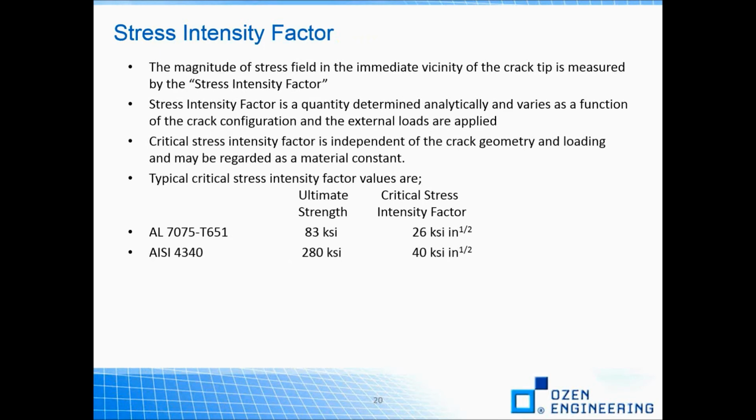So when the load and crack size are kept below the threshold point of unstable crack extension, which is region number 2 if you remember from the earlier slides, the magnitude of stress felt in the immediate vicinity of the crack tip is measured by the so-called stress intensity factor, and it is associated with the stresses. The stress intensity factor is a quantity determined analytically and varies as a function of the crack configuration and the manner in which the external loads are applied.